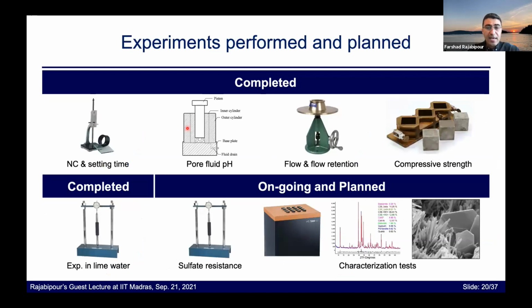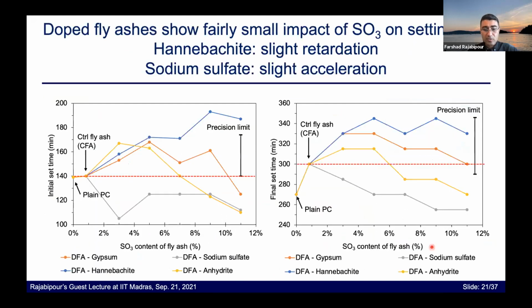We looked at setting time, pore fluid pH, workability of mortar, compressive strength of mortar, and expansion. We also have some tests that are currently ongoing or planned, such as sulfate resistance, and some of the more characterization tests such as calorimetry, X-ray diffraction, and SEM. I'm going to share some of these results with you in the coming slides.